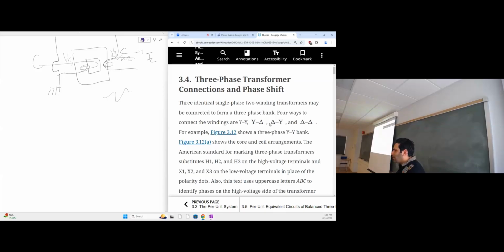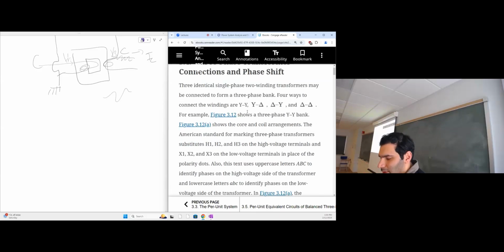How much would that IN be? In the regular case, it would be zero because there will be no excessive current flowing, so IN will be useless. But it's very important in case we had a fault, we should have a certain path for that extra current to get out of the circuit.